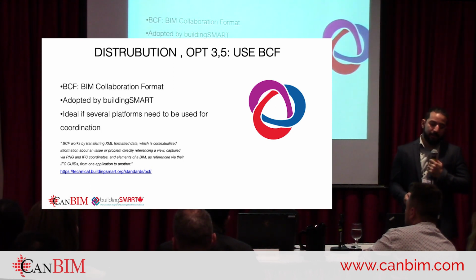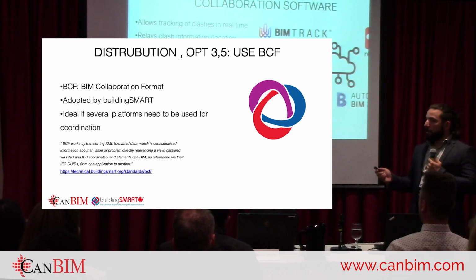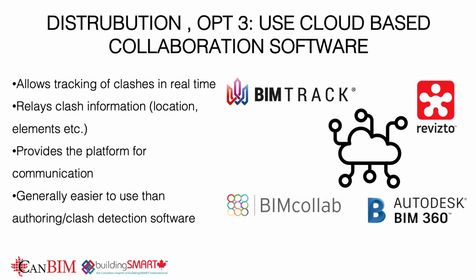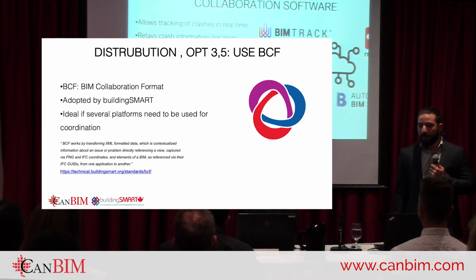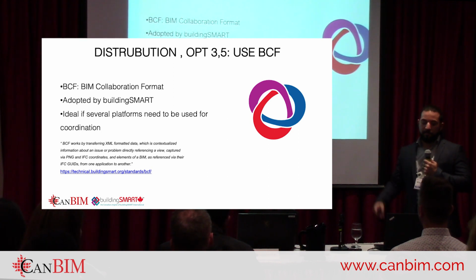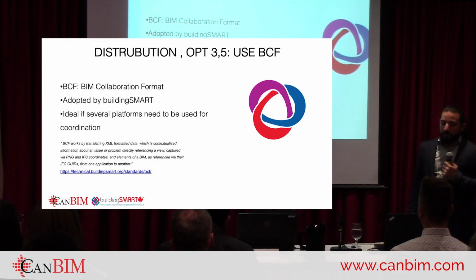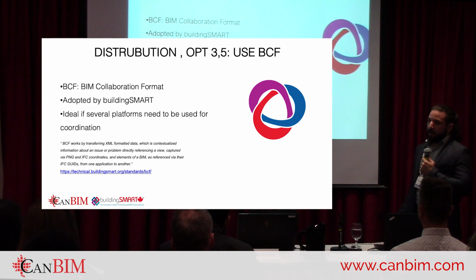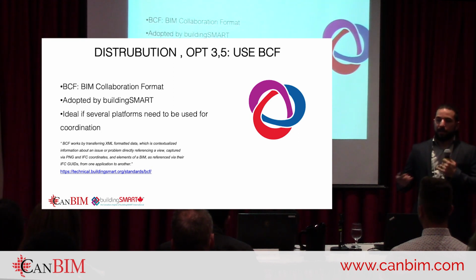And the nice thing about this is if you're using any of the software here, a lot of them also work with BCF. So if you had a case where people insist on using different software, it works even with authoring software. Revit even has a kind of BCF input. So if you have a hard time getting people on board with the software that you use, you could use BCF to exchange data.